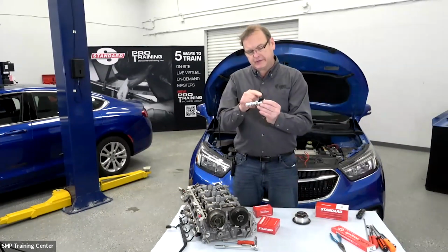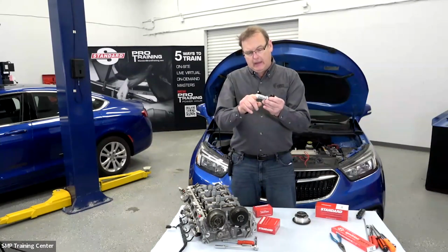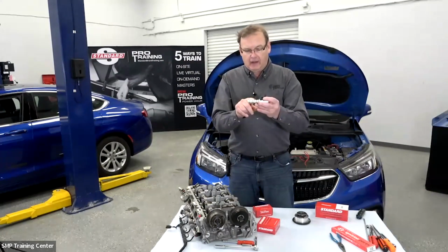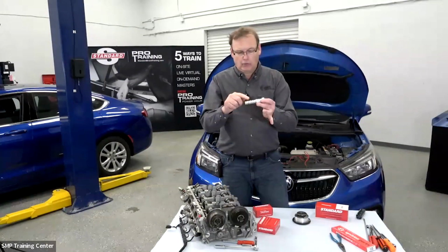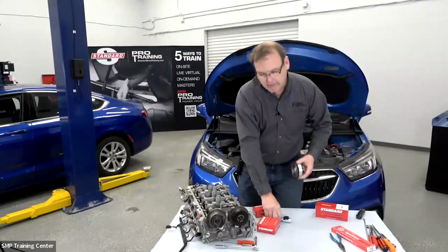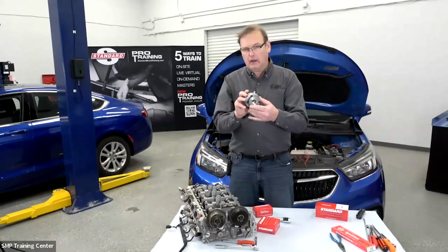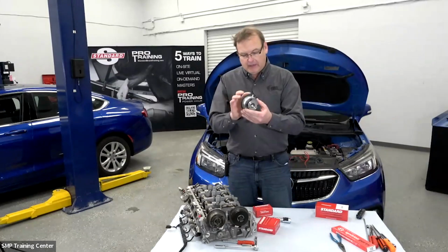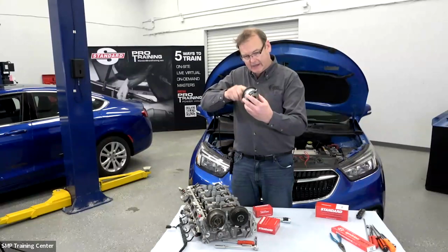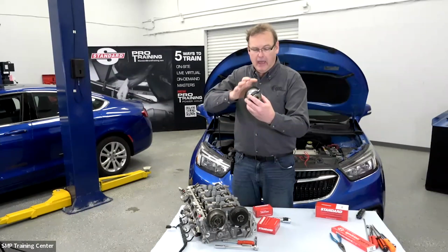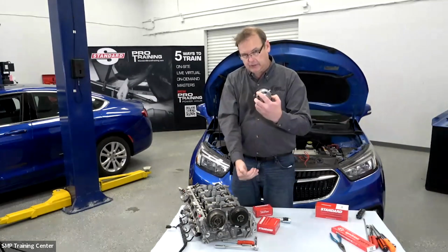Now, the oil control solenoid will be duty cycled. The control module will duty cycle a signal to the solenoid to direct a spool valve inside of the assembly. That'll cause the spool valve to move into an appropriate position, which will then direct oil pressure into the appropriate channels that will then feed that oil pressure into the actuator or the phaser. Now, inside of the phaser, we have a mechanism that will allow for the camshaft to be re-indexed in relation to the outer gear as the gear is being driven by either a chain or a belt, which changes the camshaft's relationship to the crankshaft.